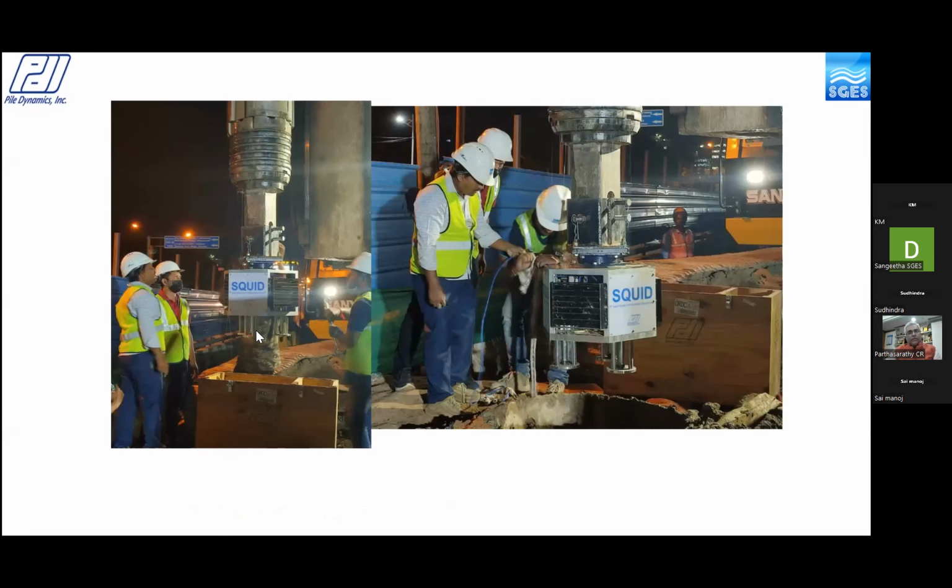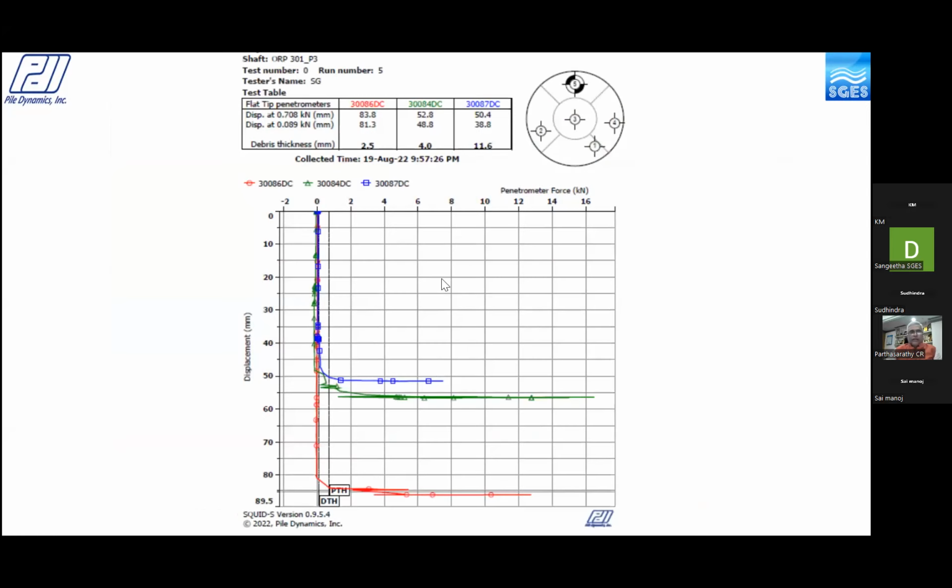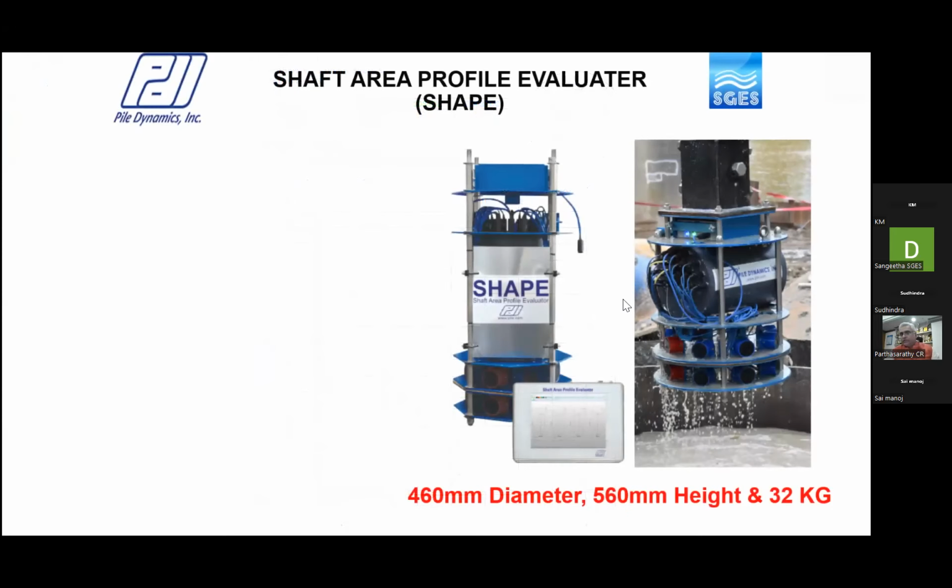So in another project, the same thing happened, but there were several cleaning processes, about 4 to 5 times. Later on, when you finally tested, the thickness of contamination was less than half an inch, which is prescribed in some of the federal highway guidelines in the US, and the same thing could be adopted here. And then the reinforcement was lowered down and the concrete poured. So this SQUID will estimate quantitatively the thickness of contamination at the base of the pile borehole in order to not experience large settlements during the static load test.